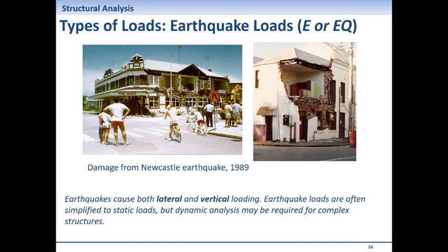There's another way of categorizing loads. We have another two categories, static loads versus dynamic loads. For everyday structural engineering, the majority of cases, we only deal with the static loads. Even when we design for earthquake and wind, which are in nature dynamic, they are moving, yes, there is inertia involved. We use approximate methods to estimate them, and we use equivalent static loads.